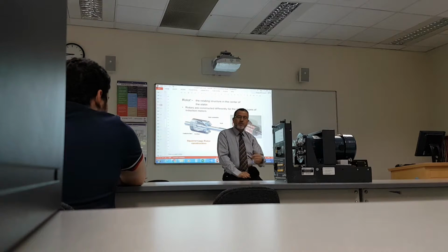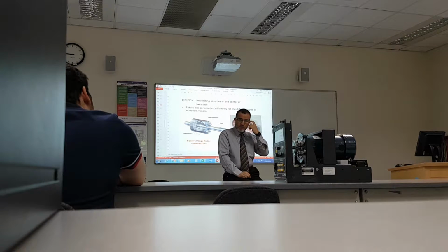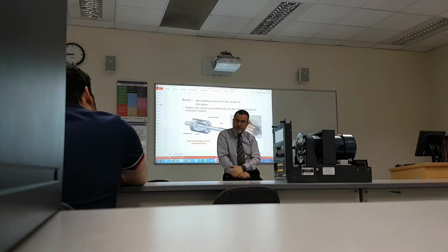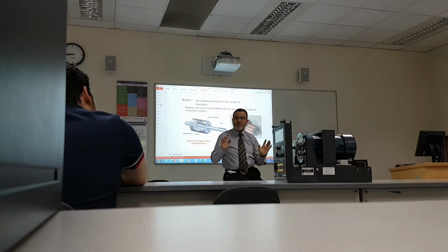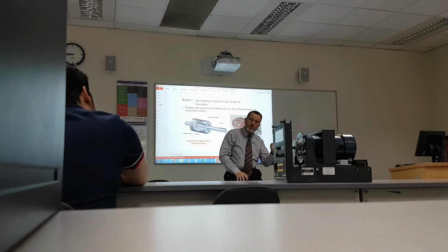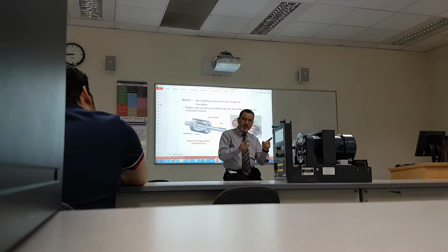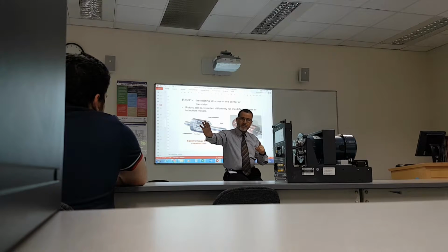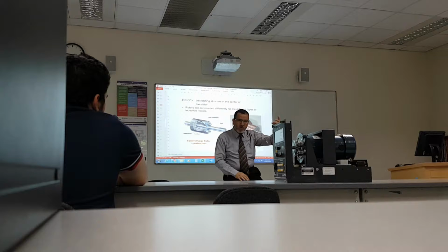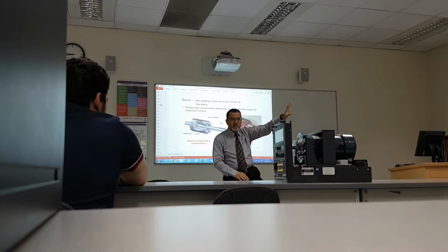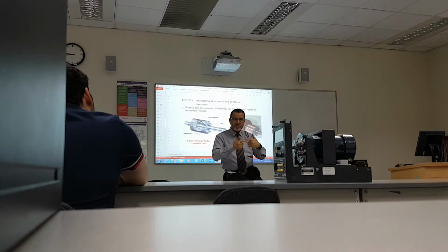Usually motors have overload protection. So the overload protection will eventually cut the power, stop it altogether. It's not stopping because it doesn't want to go, but because you're overloading. If your protection is working properly, it will guard it from being burned. If your protection is not working, and you keep adding more load beyond full load current, eventually it will burn. The insulation on the windings will melt. There'll be a short circuit.